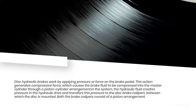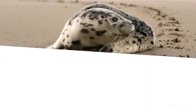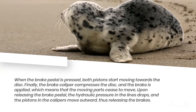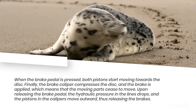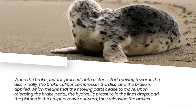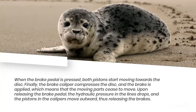Both the brake calipers consist of a piston arrangement. When the brake pedal is pressed, both pistons start moving towards the disc. Finally, the brake caliper compresses the disc, and the brake is applied, which means that the moving parts cease to move. Upon releasing the brake pedal, the hydraulic pressure in the lines drops, and the pistons in the calipers move outward, thus releasing the brakes.